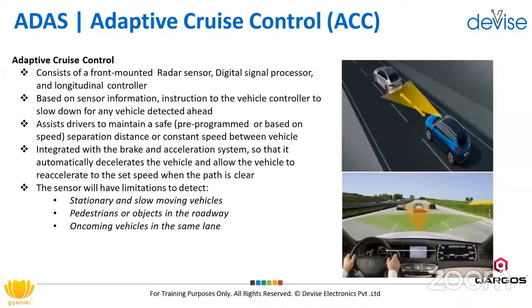Adaptive cruise control is one of the best examples of an ADAS system, and it could be categorized as level 2 or level 3, which we'll see in the subsequent slide. This principally works with a radar sensor, and a distance is set for the vehicle to take control of. In the ADAS language, or when we're talking about functional safety, latency plays a role. When the software code is written, when should this functionality come to a stop? This is already predefined. If the distance is going to go low, and there are multiple sensors to vouch for warnings, the adaptive cruise control will come in.